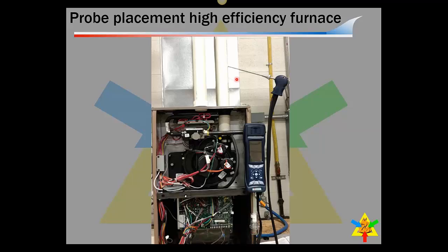On water heaters and mid-efficient furnaces, I personally don't care if you plug the hole or not. That being said, sometimes people freak out if you drill a hole in their flue and don't put a plug in it, so probably the best practice is just plug them. But at the end of the day, if you don't plug those holes, nothing bad's going to happen. Okay? They're negative pressure flues. When they're working right, they'll suck air into the hole. These ones are different. They're positive pressure. We absolutely have to close that hole off.